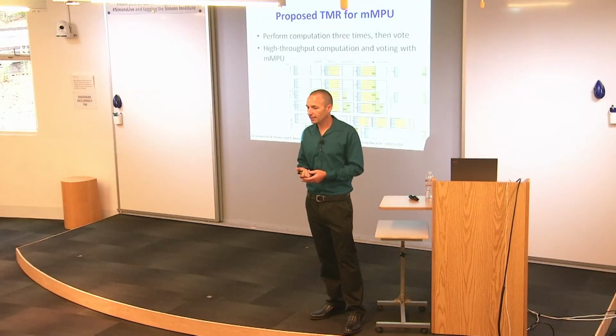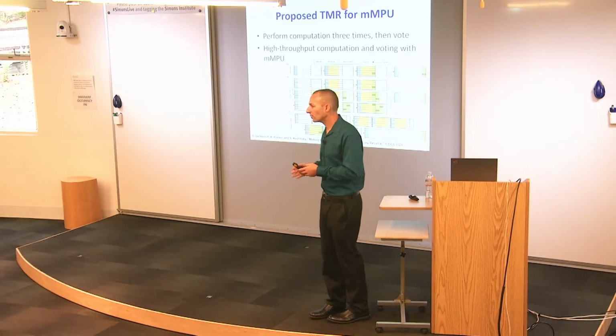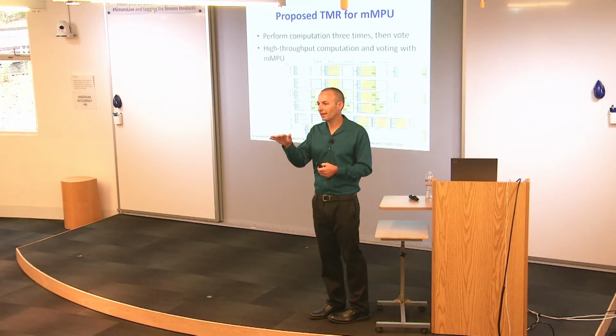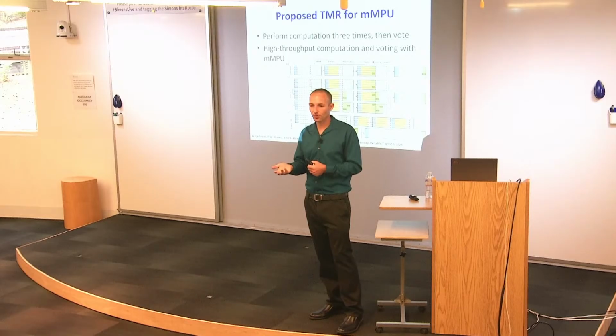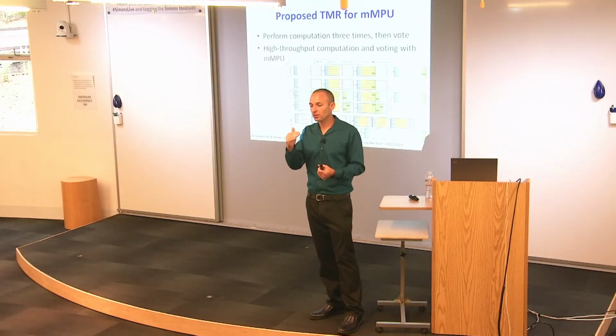For direct errors, we also use triple modular redundancy. And there are different ways to do that. One way is to do it within the same row. So you can think about having the 3 gates in the same row, paying 3 times the latency that is required. A different approach is to use row parallelism. So we will use 3 rows for the 3 gates that will be performed. This way, the latency will remain almost constant besides the votes that are required in the end. But we will lose a lot of area because now we consume 3 rows instead of 1 row. Okay, that's the trade-off.